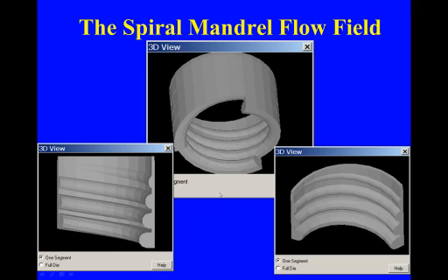So here I've made a die that has roughly similar characteristics, and because of the periodic nature of this geometry, we only need to analyze one section between ports. You can see here that we have basically in this die 3 inlets, and so this one section repeats basically 3 times. So to make life easy, we always take advantage of any periodicity.